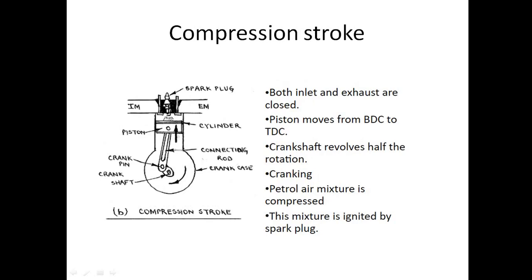This is the compression stroke. The piston is moving from bottom dead center to top dead center, and both valves are closed. Due to the movement of the piston from BDC to TDC, the suction charge will compress from the total cylinder volume to the clearance volume.